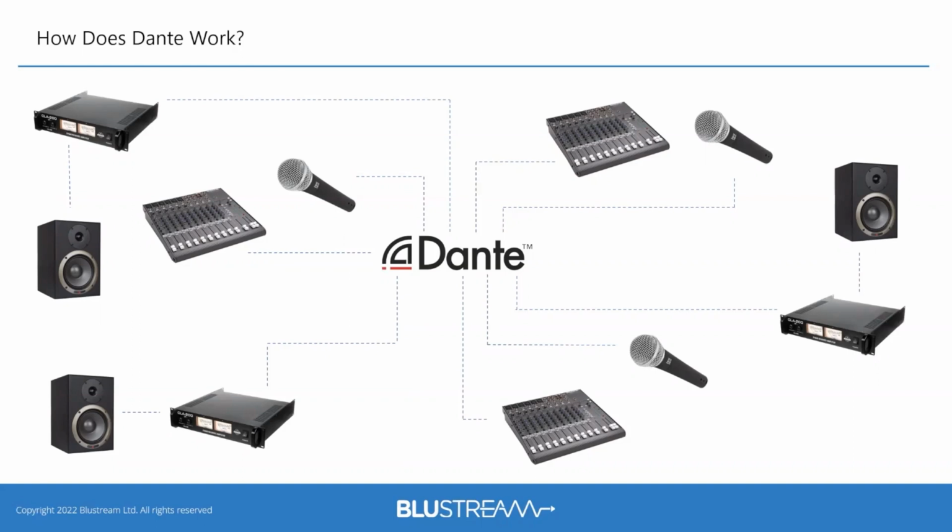The transmission of Dante is so fast, we're talking about delivery of audio that can, in many cases, be less than a millisecond. That's right, Dante measures latency of audio down in microseconds. This also means that since the hub here isn't doing much of anything other than routing the signal around, we can use switches of all makes and models. Support isn't limited to a list of specific brands or models. In fact, small Dante networks can even be used on unmanaged switches, making the cost of entry for a Dante system extremely lucrative.